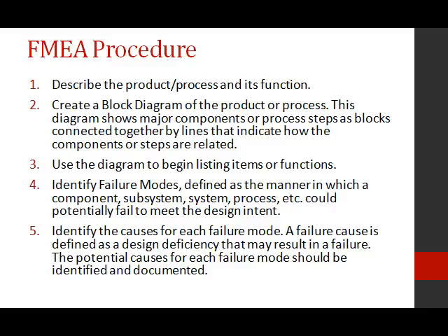4. Identify failure modes, defined as the manner in which a component, a system, a subsystem, or process potentially fail to meet the design intent. And 5. Identify the causes for each failure mode. A failure cause is defined as a design deficiency that may result in a failure. The potential causes for each failure mode should be identified and documented.